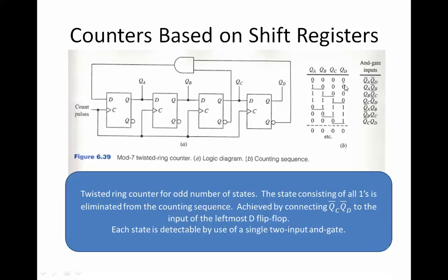So just look at these, the same concept. D comes through, which means D bar, which means 1 and 0, it passes through, it keeps passing. And at one point, it is going to check these values. Suppose it is a 0. Let us say now we have to concentrate on both C and D, the values of C and D. If both C and D are 0, then 0 is going to be fed in.